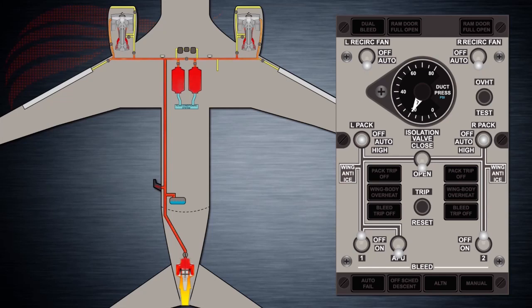In the case of engine-supplied bleed air, the thrust lever position has a direct incidence on the temperature and pressure of bleed air. If both the APU and engines are supplying bleed air to the pneumatic manifold, there's a high chance of it rupturing. The ducting is relatively thin, and therefore, caution must be exercised when selecting multiple bleed air sources for pneumatic power. A dual bleed light in the forward overhead panel is available to protect the aircraft from this condition.